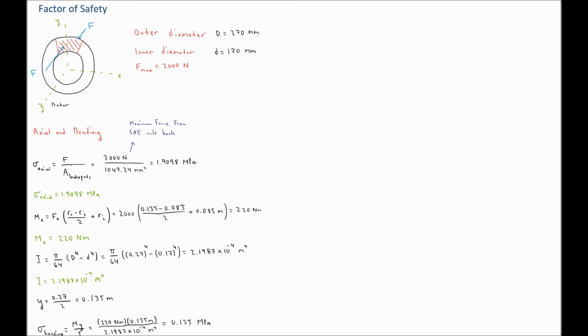Our next loading condition is the factor of safety. This is the term that essentially describes the load carrying capacity of a system beyond the expected loads. In other words, the factor of safety is how much stronger the system is than it needs to be for an intended load. This value indicates whether or not the design, which in this case is the rotor component of a FSAE disc brake, will be able to withstand the stress being applied to it.